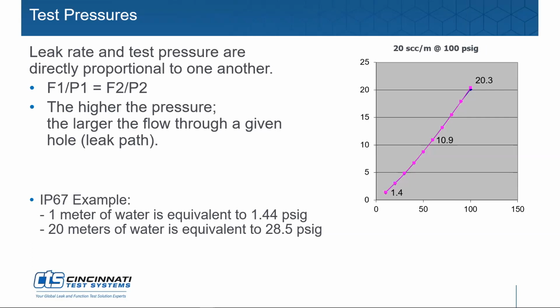Yeah, and here's another interesting example: the water pump and radiator industry right now. Originally, the spec was 4 cc per minute at 16 psi. Well, lots of water coolant systems and powertrains are up around 20 psi now, so it's 4 cc at 20 psi. As you're testing at that higher pressure, your risk is a little higher, and they're keeping the same leak rate, allowing for less risk associated with a leak at the higher pressures.